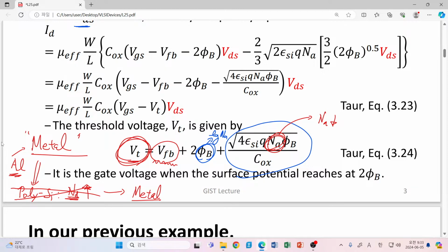We can maintain relatively low doping density, and that is critically related with relatively high effective mobility, because as I told you before again and again, mobility is highly restricted by the doping density. So now we have a certain knob to free our effective mobility from the doping restricted or doping limited value. Okay.